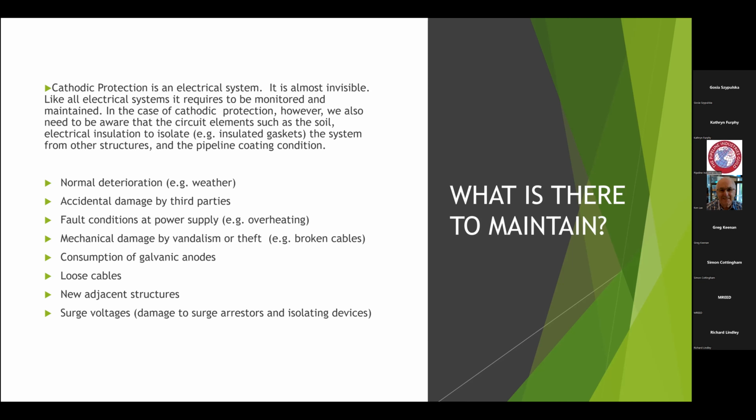But if we connect an earthing system to the pipe, the electric current would go to the earthing system because it's a lower resistance than the pipe. Because when electric current flows, rather like water, it tends to take the easiest path. That's not universally true, because actually electric current takes every single path. But because of the different resistances in all the different paths, the current that arrives in some of them is very, very small, measured in millionths of an ampere. So we have to electrically isolate it.